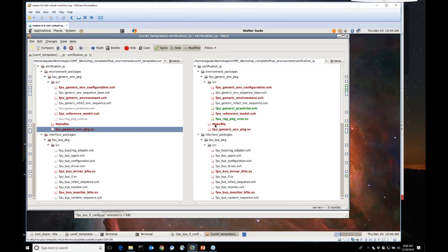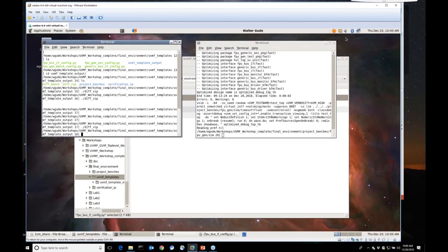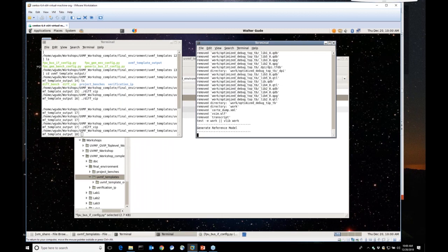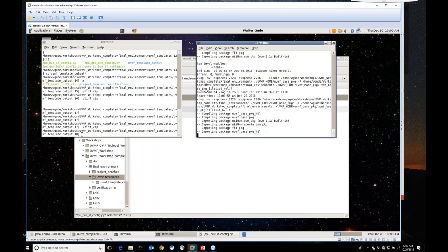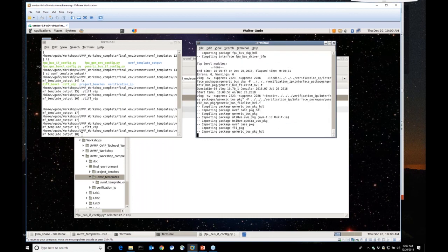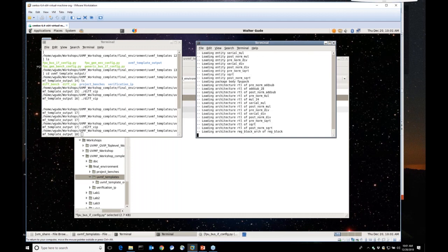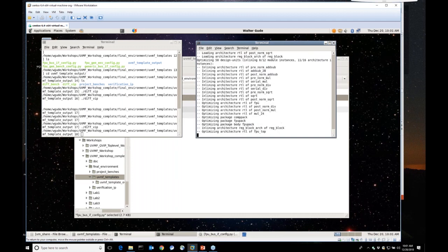And then this makefile right here will compile the agents and then compile the environment. So you see it's a fairly limited number of changes that I have to make. At the end, I did not do anything other than the changes I talked about, and I can just say make debug, and that is going to run through, compile my entire test bench, launch the simulation, and get me up and ready to be running this UVM environment.